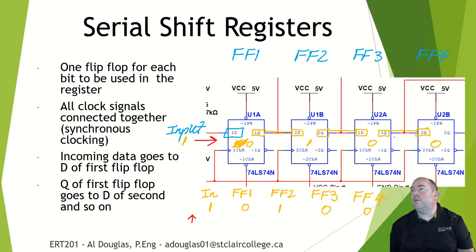We are going to look to see if our Q was on. If our Q was on here, it'll trigger the data input here. So this 0 basically moves over to here, because if Q was on, we'd have a 1. If this was a 1, we'd have Q on, which would trigger the data here, which means a 1 would transfer across here. If Q is off, in this case where it's a 0, that means this is off.